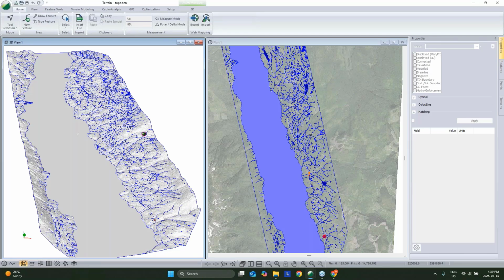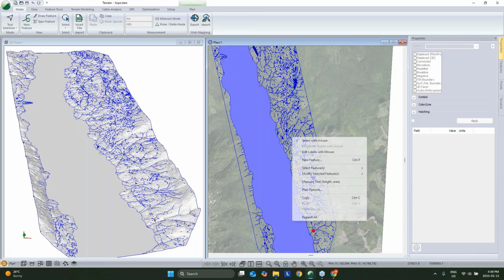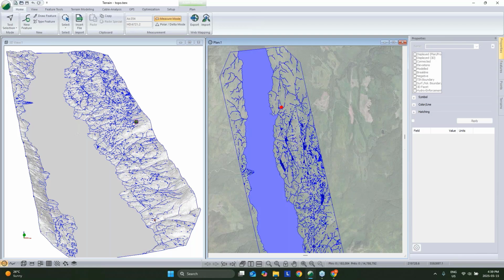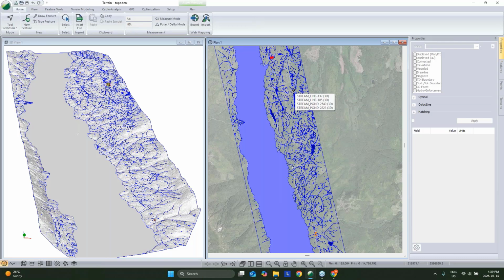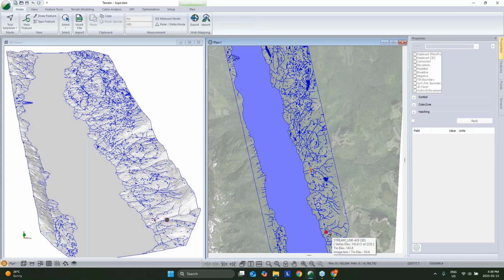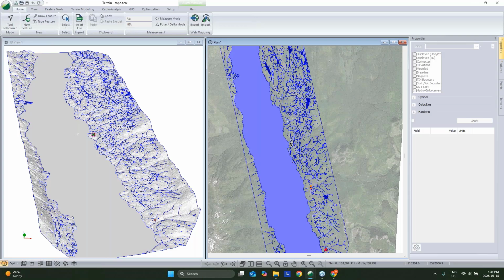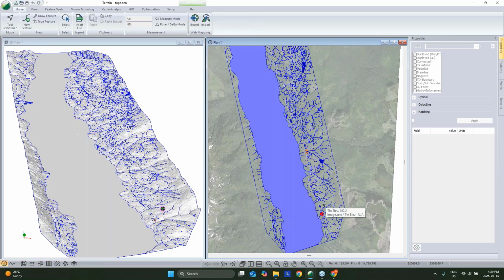So this project is a realignment project. I want to go from here up to here. The existing road is kind of that 90 km/h design speed for the geometry, and I want to bump it up to 130 km/h design specs. So it could be twinning, it could just be improving what's there, but there's a good chance here that the existing geometry isn't going to be a whole lot of use to meet my needs. So major realignments are kind of on the table.